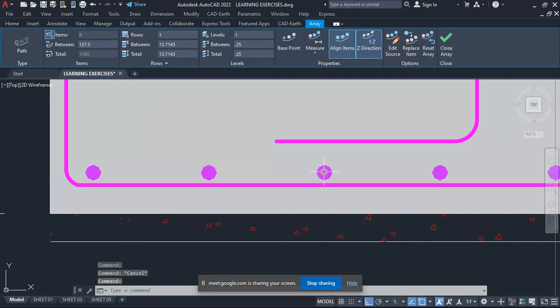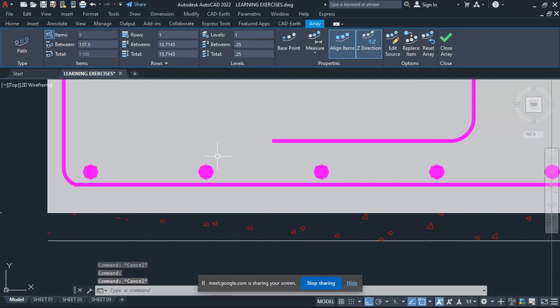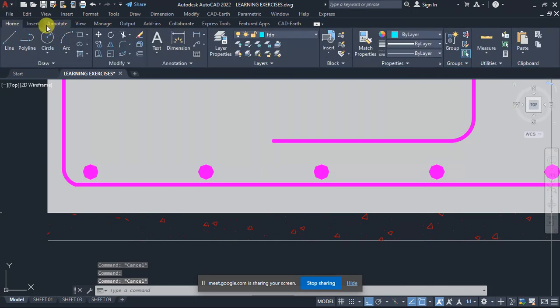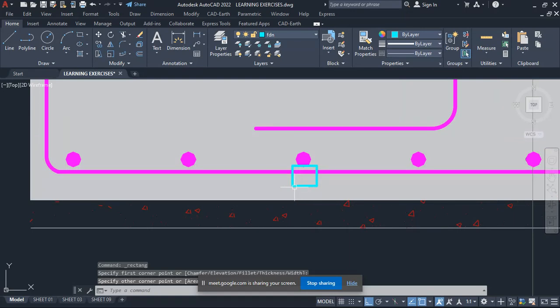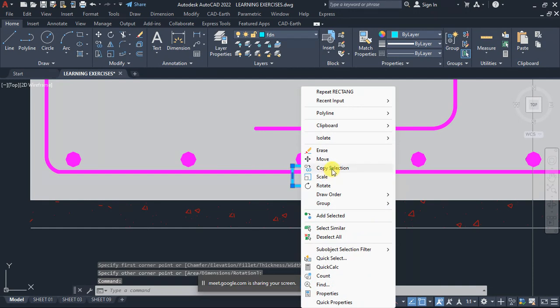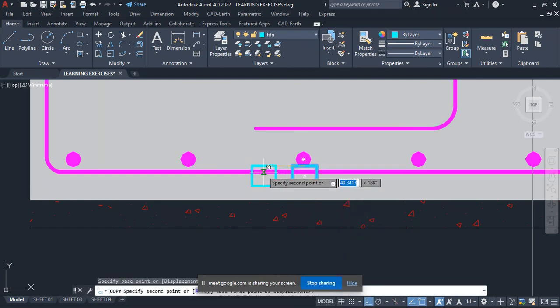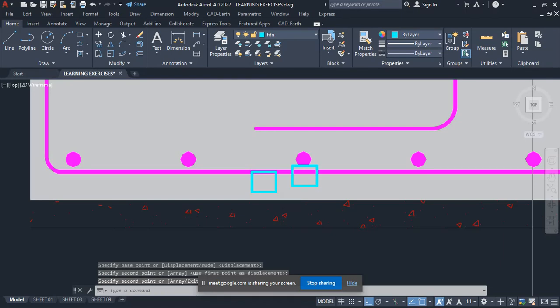So if you put your spacer on the secondary bar, that means the top bar here, say it is 50 mm, this is 50, I'm assuming this is my spacer. Do you realize that these bars will come a bit down compared to when you put your spacer on the bottom bar? You get it?